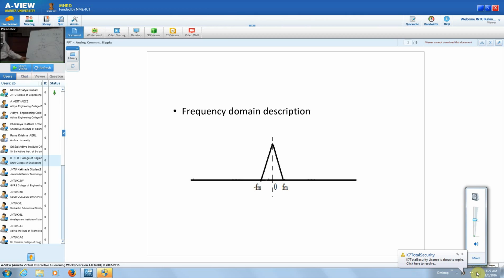All these will be coming here at your receiver, and as you look into this, the distances that the signal travels are of different lengths. That means the time it takes is going to be changing. So when the time changes, the signal frequency is not going to change, but the phase is going to change.